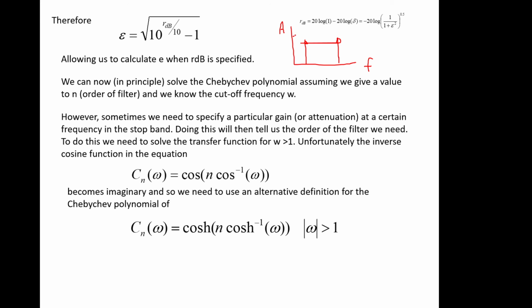So we've got our frequency response that does that. So we're interested in what's the value of the gain at this point here. And as long as our signal is reduced by this factor down here at this point, that's what we're interested in. And if we know that, we can then maybe work back through to work out what order of filter we actually need and what cutoff frequency we need to still allow this one through.